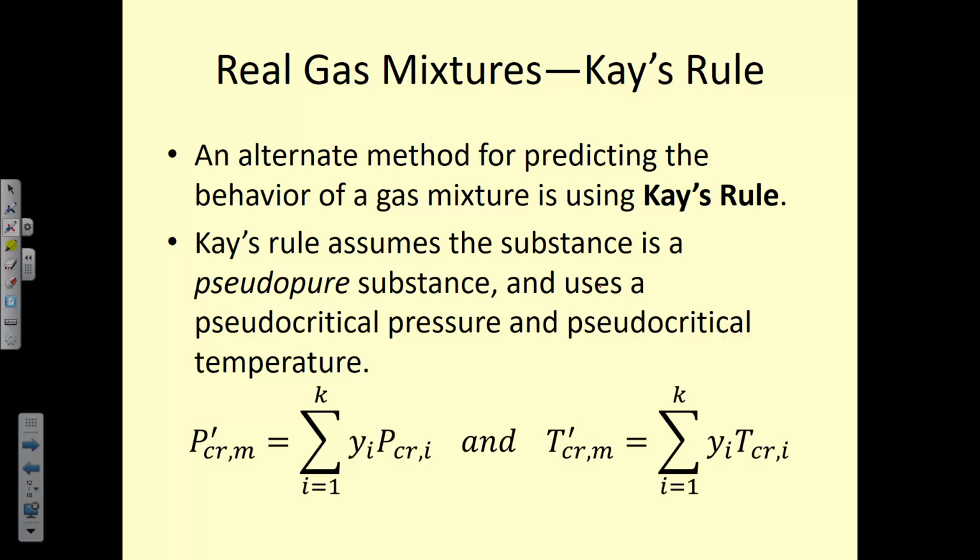It's where you're just taking sort of like the lump average of all of the critical points of these individual gases, and you're finding where on the map approximately you would be. And you're using the molar fraction, because if you have a larger quantity of a certain gas, it's going to have a greater influence on how far away from that critical point you place it, right? So it has a greater weight when determining where to find that average pseudo-critical point.